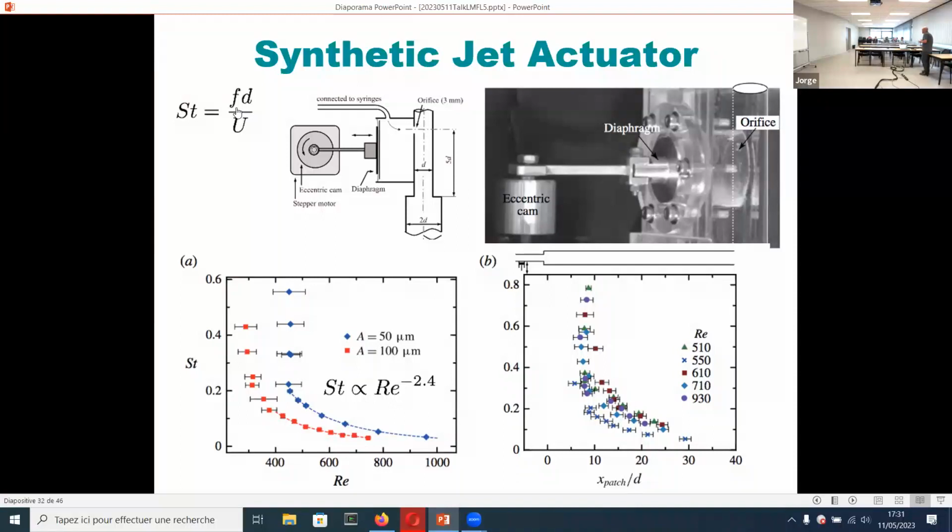Is it to find that the outcome depends on the type of disturbance? There's no universality, really. So what I say is that the threshold curve depends on the type of disturbance. Once the puff has survived for 100 diameters and it's in this ping pong ball regime where you go from one traveling wave solution to the other, then it's another story. But I think how you get into turbulence is very much sensitive to the way you perturb your flow.